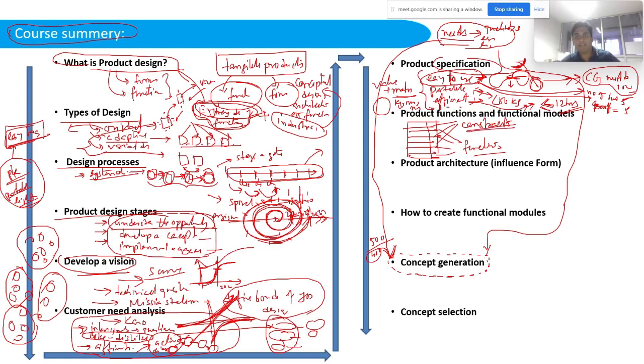That is not something a designer has to plan to compromise on various functionalities. A functionality is something like engine power should be at least 35 bhp. Achieving 35 bhp is a functionality that he needs to meet with the design of the cylinders or engine piston. But the weight of the bike, which at the end needs to be less than 180 kg, is a constraint.